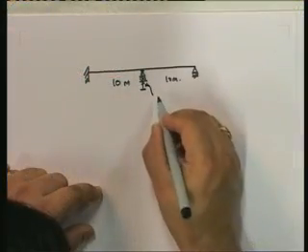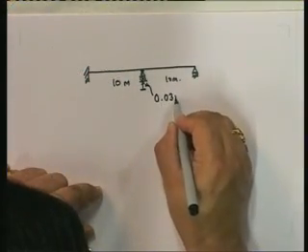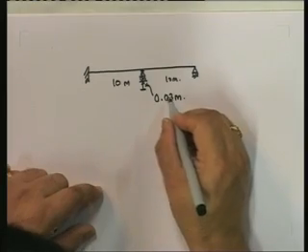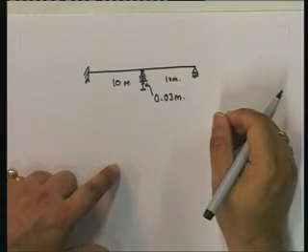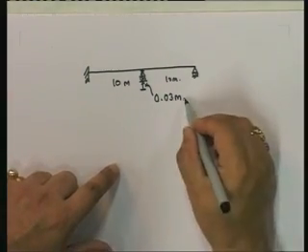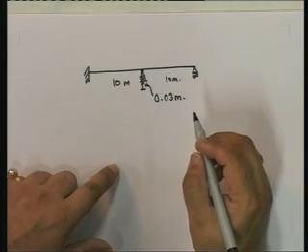And when you have linear elastic structures, you can always superpose. So let us say that, in addition to the loading we considered in the previous case, this support settles. We have already found the effect the load has. Now we want to find the effect this settlement has. Let's assume a particular value, that it goes down by 30 millimeters, or 0.03 meters.